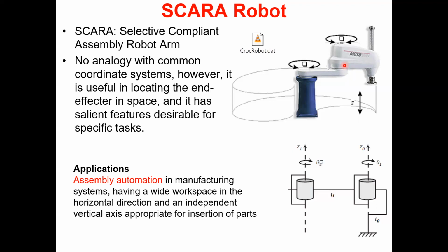Why is that? Gravitational effect. Because of gravity. So the shoulder joint needs to produce additional torque to counter the gravity. To maintain that position, we have to counter the gravity. Gravity's effect is maximum when the arm is horizontal, at 90 degrees. So that is why you feel it a bit difficult.